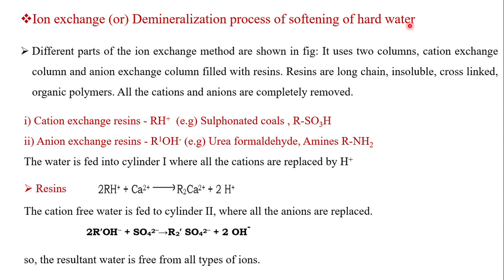This hard water we can't use in boilers. You know the limit for boiler feed water is less than 2 ppm. Also you know the ions responsible for this. In the earlier classes we discussed that both anions and cations are responsible. The cations are calcium Ca2+ and Mg2+. The anions responsible for the hardness can be bicarbonates, but bicarbonates can be easily removed, just by boiling.